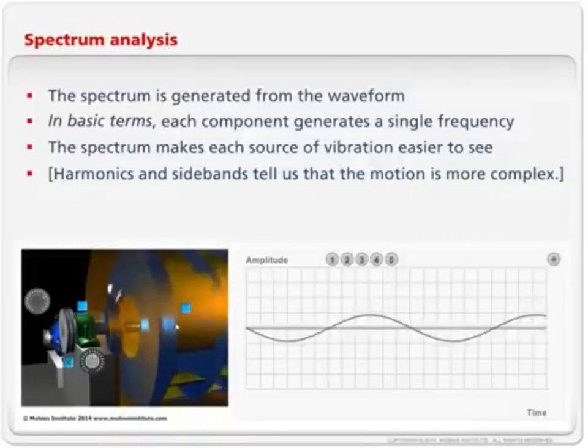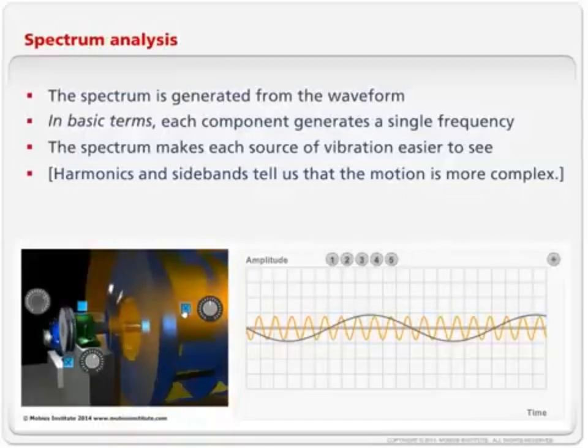I'll just give that a bit more vibration with the fan. Now, it's an orange fan, so let's make some orange vibration. Let's say there were 14 blades on the fan. I forget how many there are actually, but we get then 14 little pulses of vibration for every rotation of the shaft. Now, we're not measuring over here. This vibration that's generated because there's something, maybe the blades are bent or something like that.